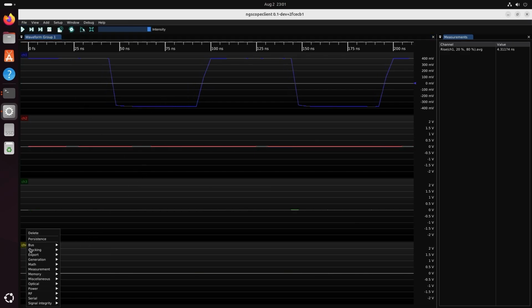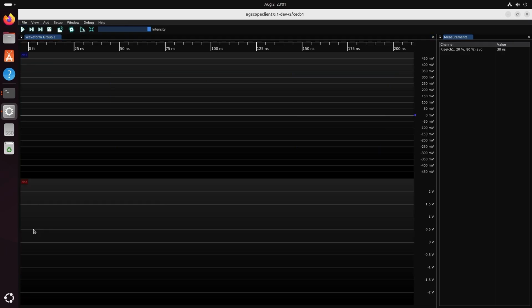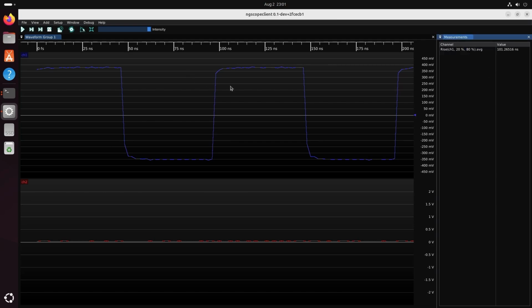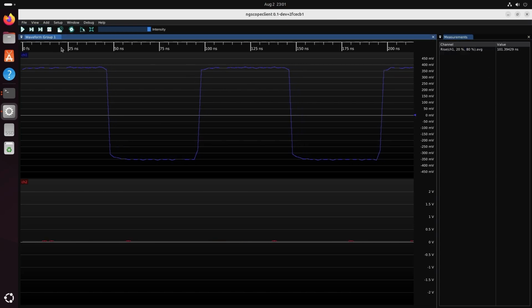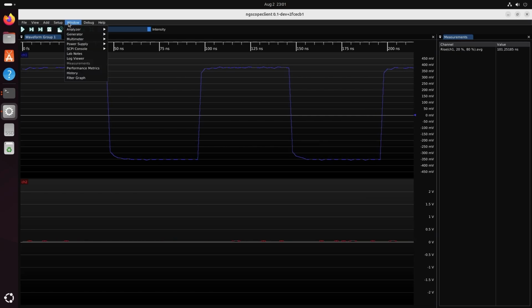So let's turn off 2 channels, see how it looks then. All right, now we're starting to see some things, but still, that's pretty much one sample there. Maybe 2, I'm not sure if that's 90. Oh yeah, here's the rise time measurement. Let's actually just change that. I can show you how to do that.